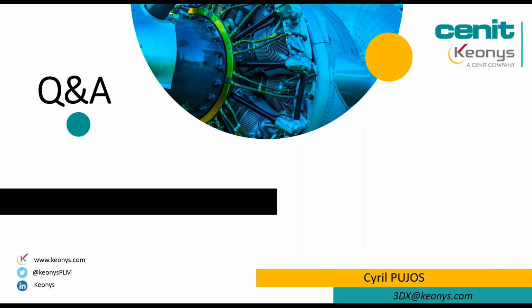There's a question here: is there a maximum number of loads or gauges? TrueLoad doesn't have any design limitations for the number of strain gauges or loads or mesh size for that matter. It's basically your computer hardware limitation. I've done projects with hundreds of strain gauges and hundreds of load cases.